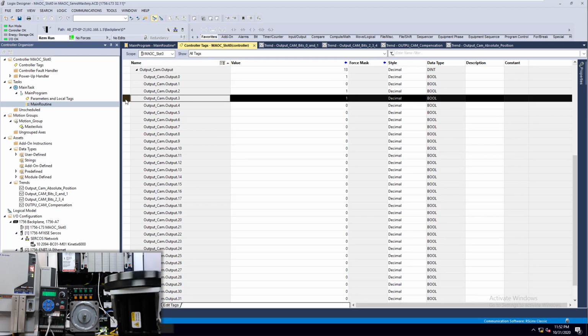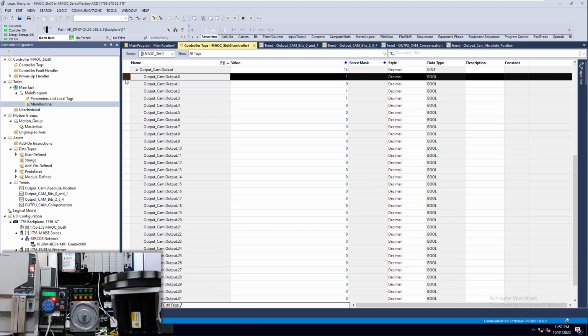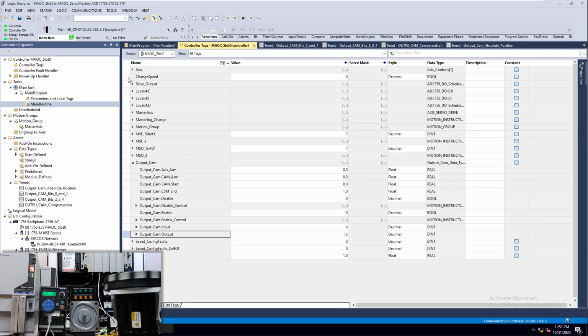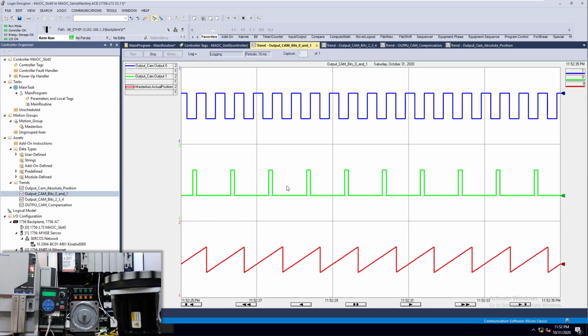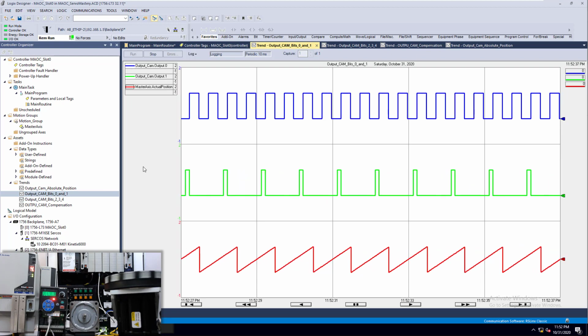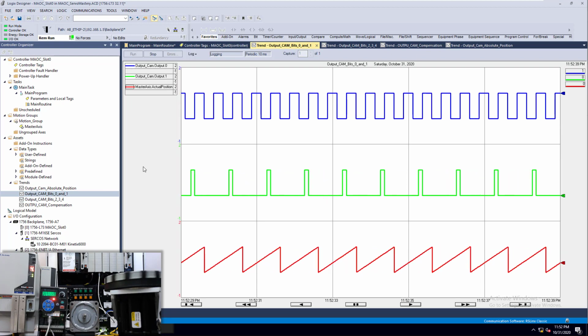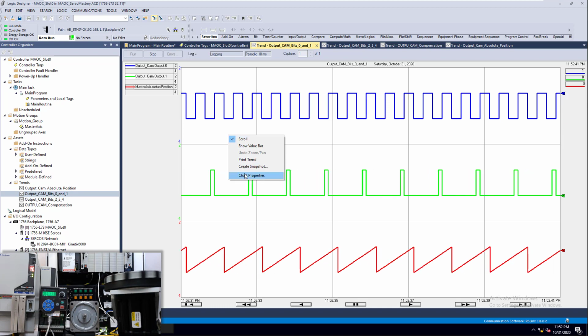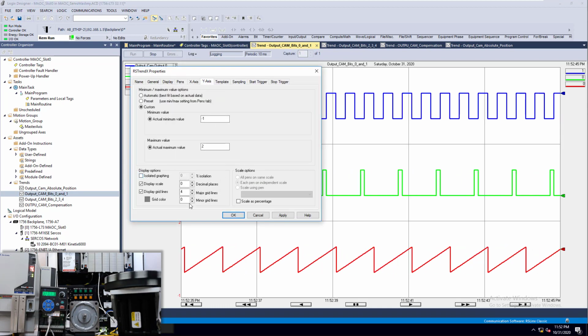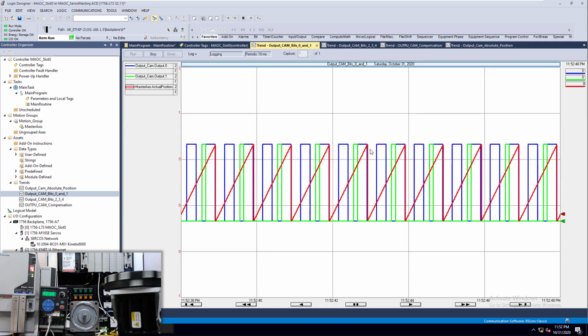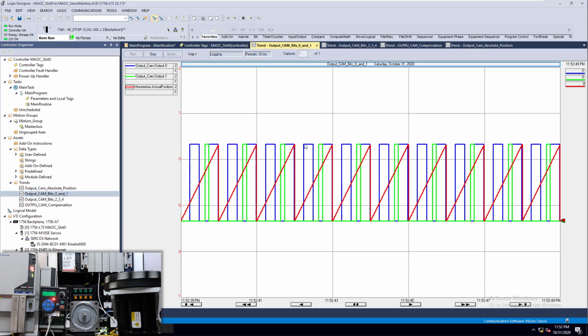This is like, say for instance you were looking at your output card, you would be cutting on these actual outputs. So let's come in here, see that, and let's see the outputs coming on and off. This is why I do a different style trend, because if I don't do an isolated graph, then it looks like this. Kind of hard to read, right?